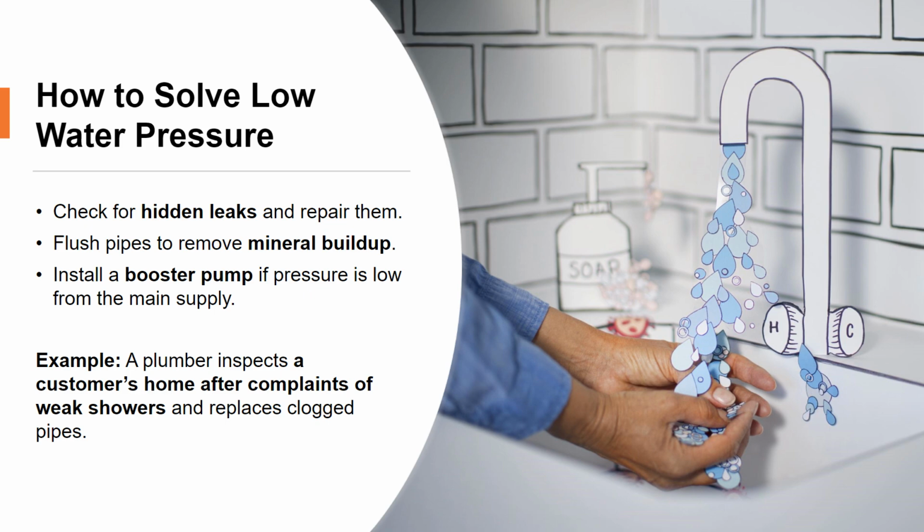Ensure valves are fully open. Check main valves, gate valves, and service line controls. Half-open valves are a common cause of unnecessary pressure loss. Use pressure-boosting solutions. If the supply is weak, consider installing a booster pump, pressure tank, or changing the pipe size if undersized.